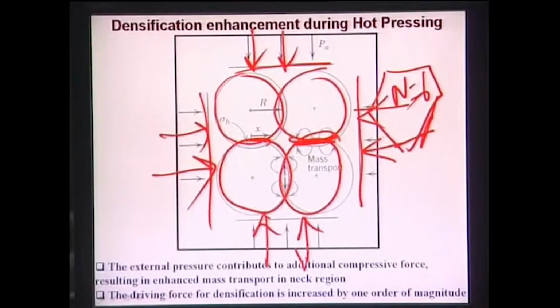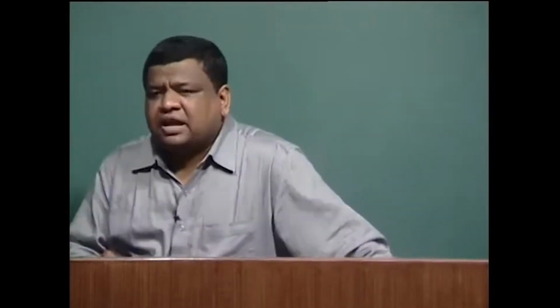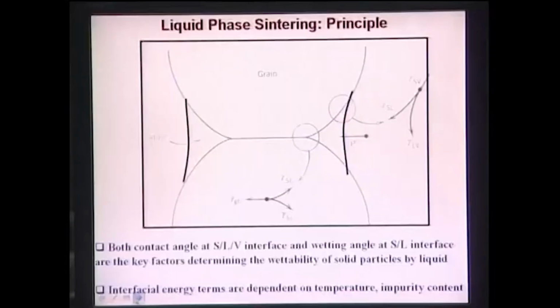Now how do these grains form? You can understand that this edge must be a part of one particle, and this edge must be part of another particle, but due to the external pressure application and the fact that only longitudinal displacement is possible, not transverse, the particle boundary becomes more flat, and that is how this entire grain structure evolves into an equiaxed grain morphology.